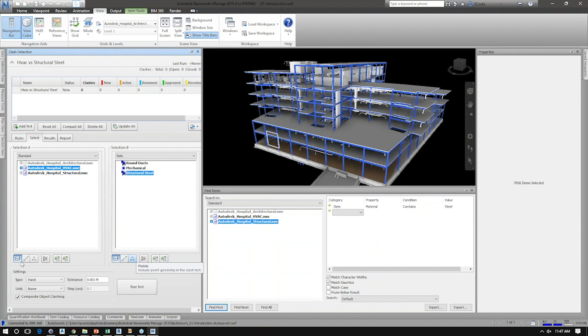You can clash surfaces, which is what we want to do. Lines and points, again, those have limited uses. Point clouds would be an example of where you'd use points. You can also choose whether or not to test self-intersecting elements. And then there's 4 types of clashes. This is probably the most salient point of this discussion, which is what are you clashing?